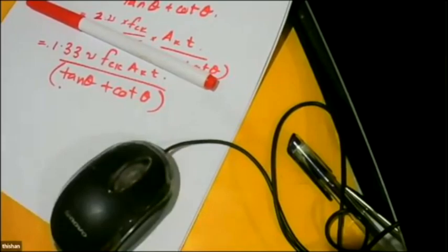For a long off-center wall, at which intervals should rigid links be projected out from the structural beam? No, you don't do that. What he says is there's a very long wall, and how many rigid links should be provided? In that case, you must not. If the wall is very long, that means you have a very heavy load on the transfer beam. Then you must, one way or the other, bring it to the center.